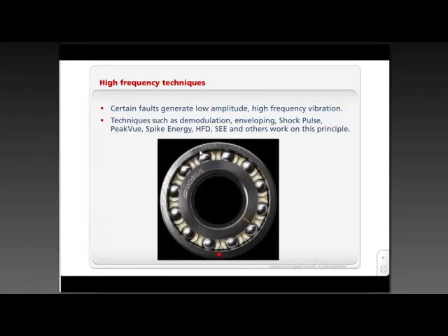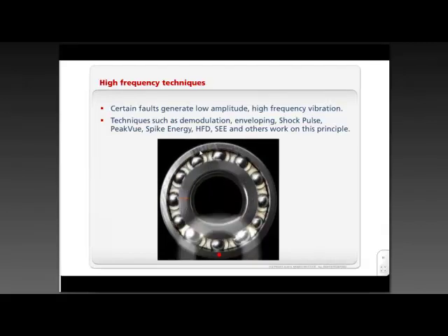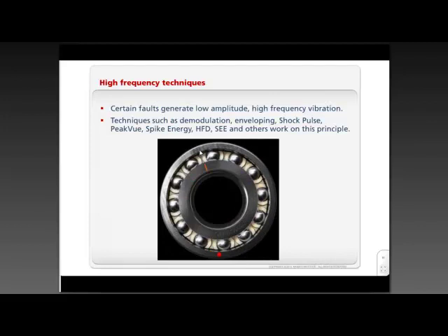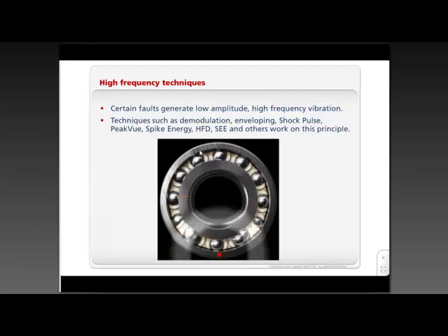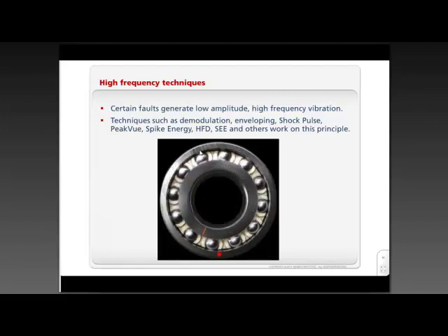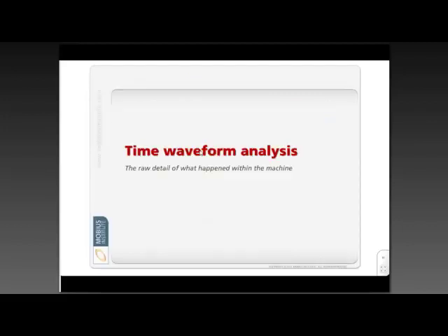What we're going to do is filter out all the low frequency vibration from the unbalance and misalignment and these sorts of faults, and we're just going to focus on what is quite high frequency vibration at a very low amplitude. And those techniques are sensitive and therefore give us a nice early warning of the problem. So that's great. And we can end up with a spectrum from this with just those frequencies, and we can use it. But wait, there's more.